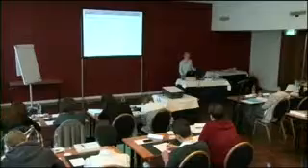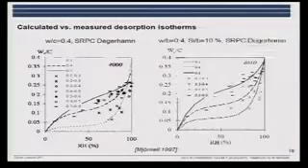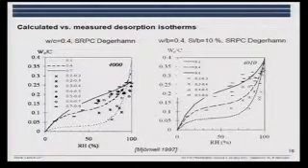This is for one cement, water cement ratio 0.4. If we add silica fume, we get a slightly different sorption isotherm. We see again the trend that initially we have much free water, and then the gel part is increasing as a function of the relative humidity.